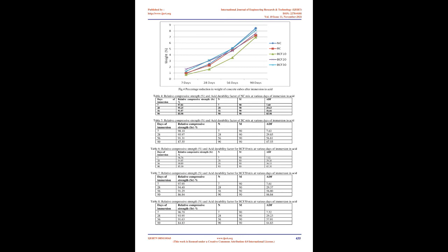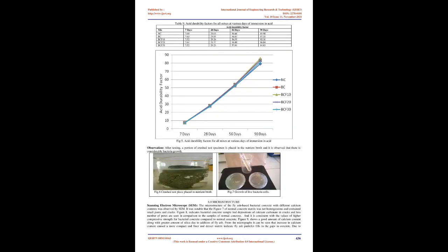4.0 Experimental program. Cross-sectional area calculated from the mean dimensions of the section in mm². 4.2 Split tensile strength test. A diametric compressive load will be applied along the length of the sample at a continuous rate until failure occurs. This loading induces tensile stresses on the plane containing the applied load, causing tensile failure of the sample. IS 5816:1999 formed the basis for the development of this procedure.